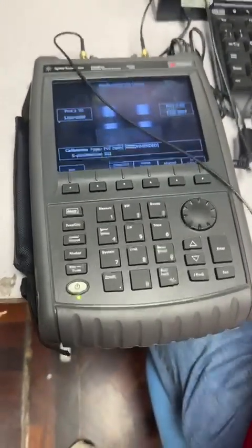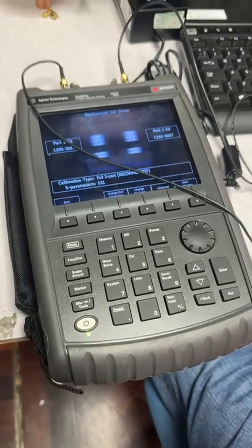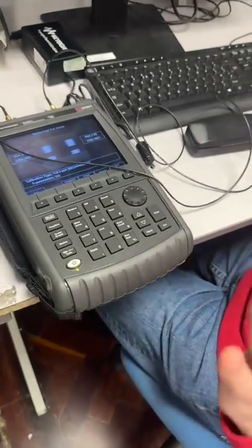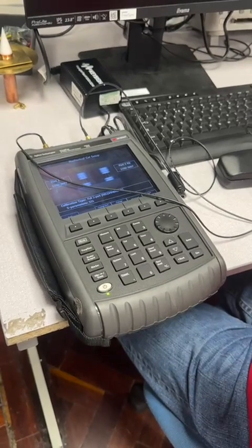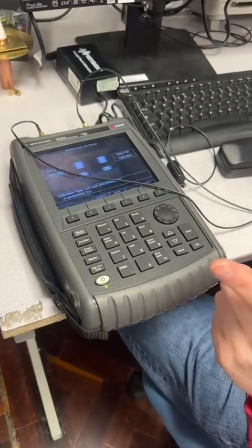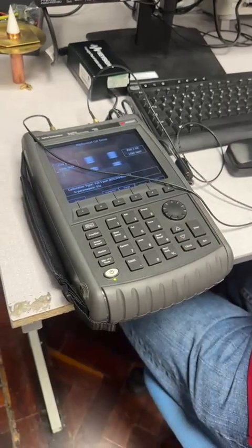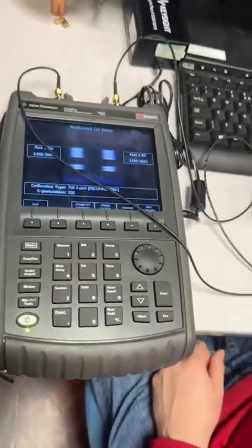There is also, what about isolation? There is an isolation cal as well. You never need to use that. I've never needed to use the isolation cal. I've just done full 2-port. So that's 3 standards on each port, and then the through, and you can do any measurement you want. The isolation calibration, you shouldn't need to do it. Okay. All right, and that's it.